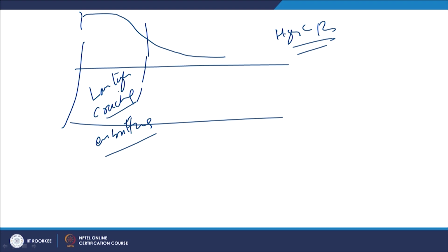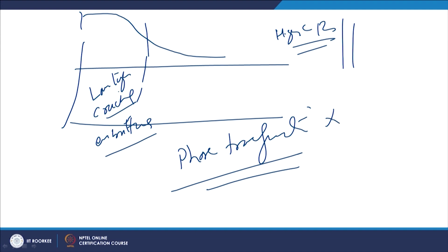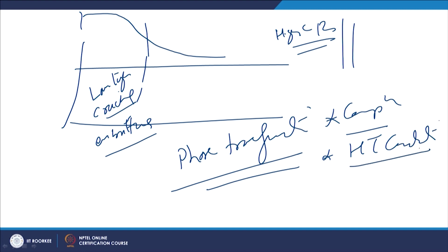But all the steels are not sensitive to this kind of phase transformation. The type of phase transformation is to a great extent a function of the composition, the heat treatment condition of the base metal, and the kind of heat input being given in the form of net heat input. Net heat input is a function of the welding process.